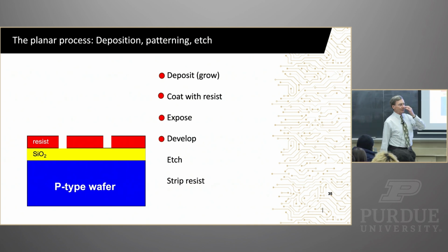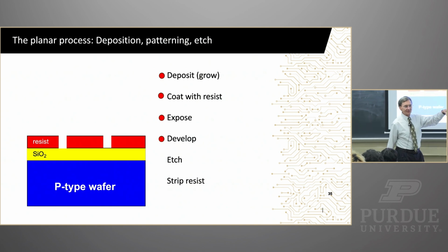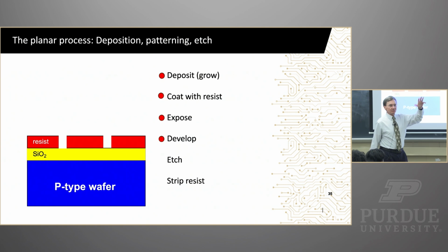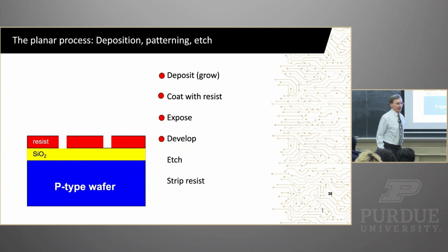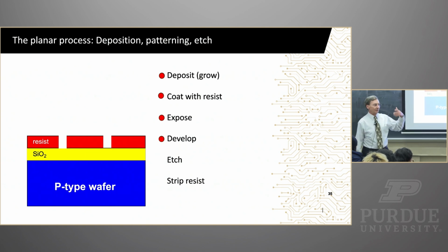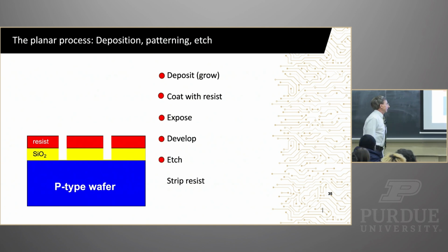Photoresist, when you put it on, is like pancake syrup. You bake it out a little bit, and it becomes more like plexiglass, but it's still this organic layer on the surface. But what you almost always do then is use that to transfer a pattern into the underlying silicon wafer. In this case, we had this oxide region, so we're going to use it to etch the oxide. We put it into either a wet chemical bath or, more likely these days, a dry etch, some kind of plasma etch, to etch it away. And so we remove that silicon dioxide region.